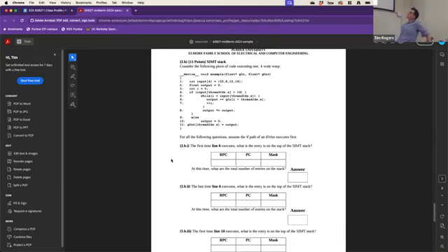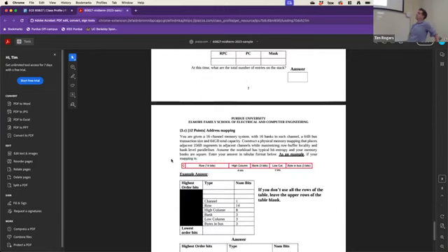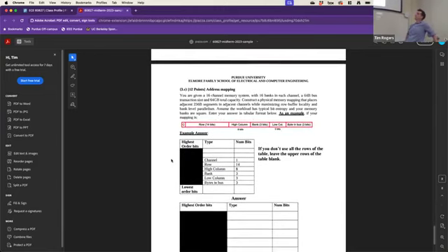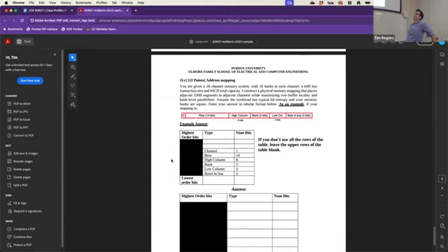And then some questions about the SIMT stack. Again, that piece of hardware, talking about reconvergence PCs, seeing if you understand what's happening with that stack, and then a little bit on the memory system. In this exam, I asked you about physical mapping in the memory system. You had to understand how many bits were associated with each thing and how you would stride the bits to maximize entropy in certain places and avoid conflicts. All that we talked about on memory system mapping was tested in these questions.